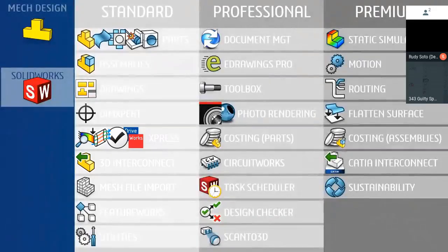That's the tool that lets you open up the files from their native format directly into SolidWorks without translating them. So files open more quickly, and they actually retain some of their intelligent design from the native package. So you guys do work with other CAD packages here, right? Okay, so that's definitely one you want to get familiar with. If you're not familiar with it, if you email me, I can send you some more information on that.